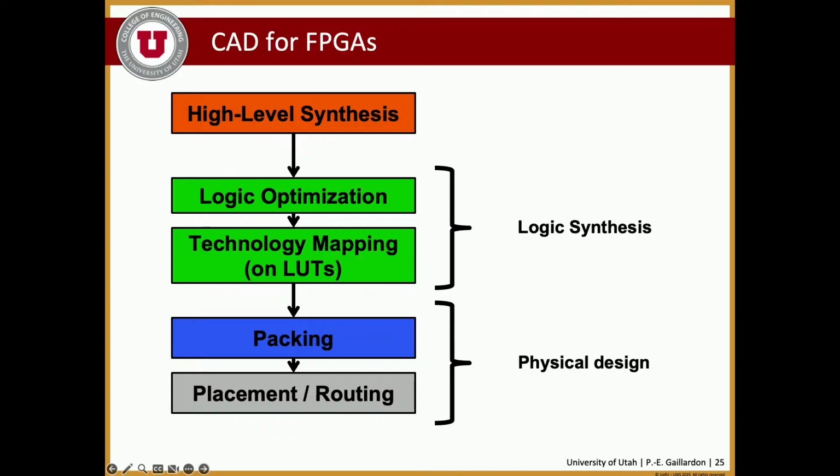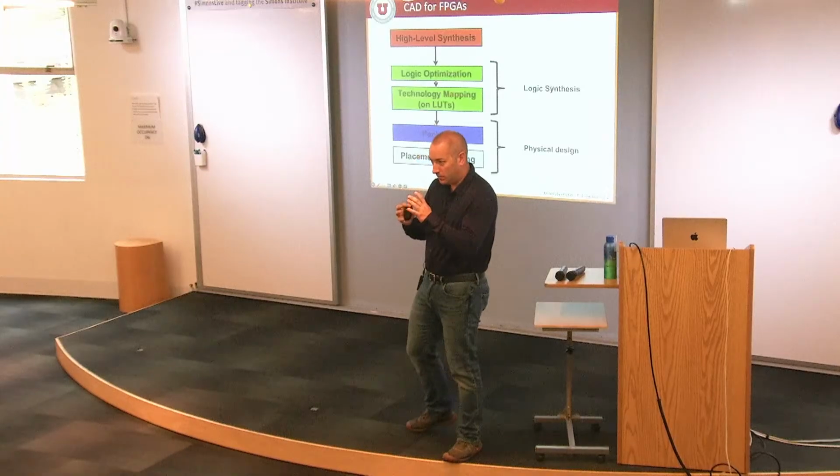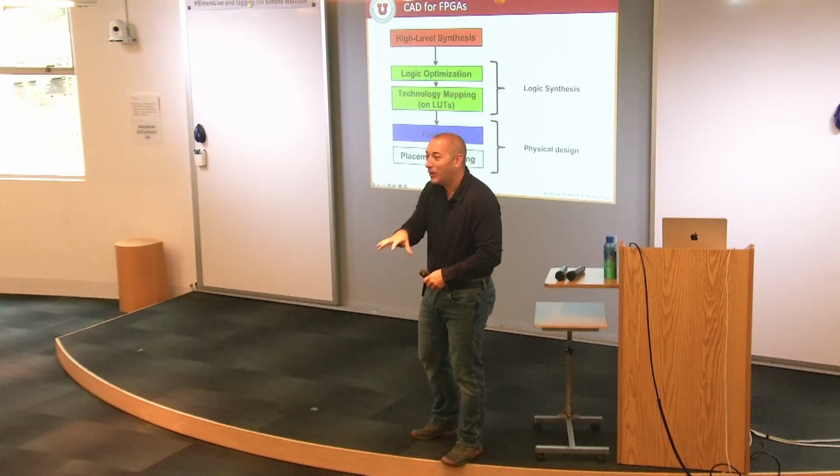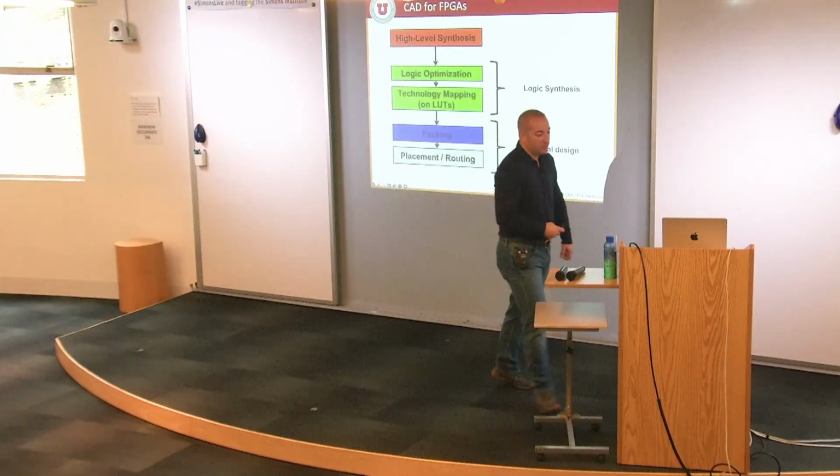So I'm not sure I entirely understand. Physical design is what you had in the previous diagram, the blocks with the multipliers and the memory and all, right? So that would be the hardware design, the hardware platform, whatever is being implemented. What we call physical design is the tool steps that will take a given application. The logic synthesis maps that to existing primitives. You know that I want to connect lookup tables and DSPs and stuff like that. The physical design step is to identify which of these logical parts should be mapped where, and then how you configure the actual routing hardware. Got it. Thank you.